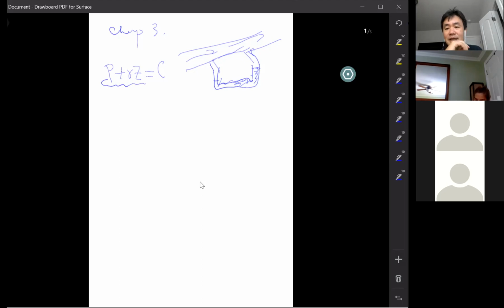Okay, this is your principle, the hydrostatic principle for the statics. Or you say piezometric head is conserved, same thing. Remember, if you divide both sides of the equation by gamma, which is rho g, it will be P over gamma plus Z. This is called piezometric head.